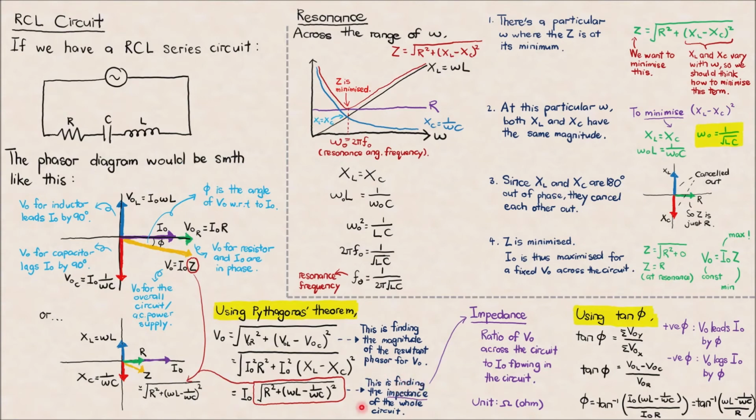If we are talking about impedance, we can redraw the phasor diagram this way. Again, this is not an actual phasor diagram like what we discussed in the previous question, because R, inductive reactance and capacitive reactance are not rotating vectors. They do not change with time. They are constant values. This is only showing you how to do the sum to obtain the impedance.